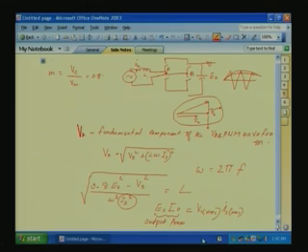E0 we know, I0 maximum load current we can find out, Vs RMS is known. From this we can find out the Is RMS for a maximum load. From the Is RMS we can find out Is peak, and square it. So, L we can find out this way.